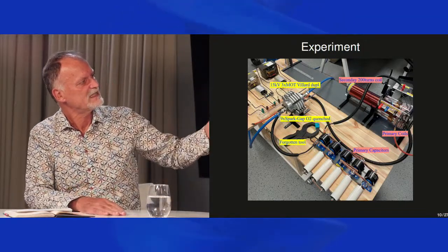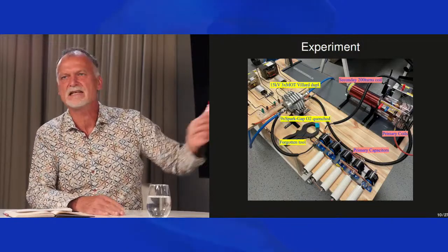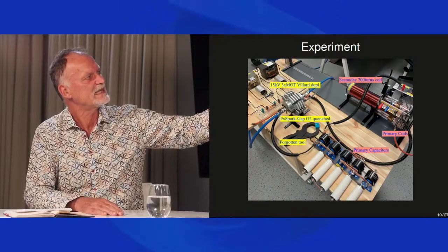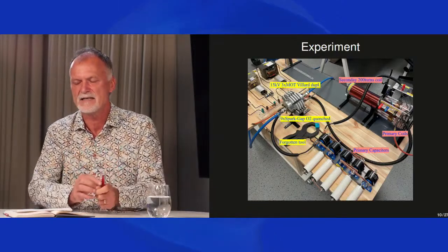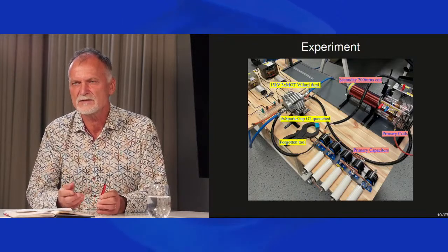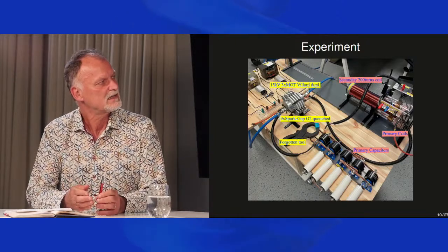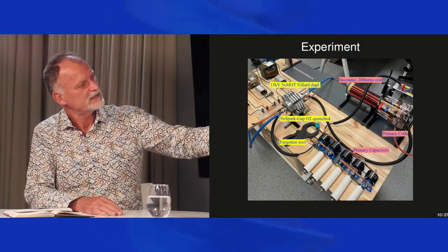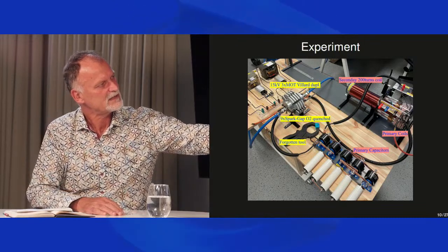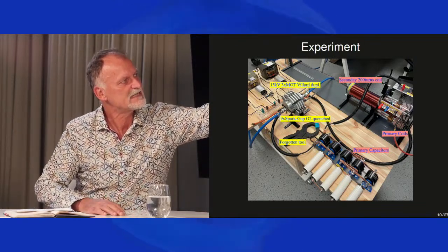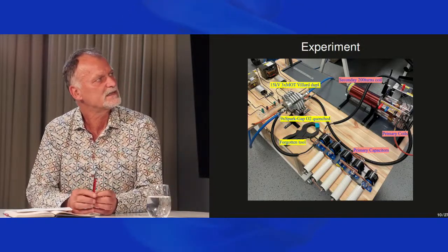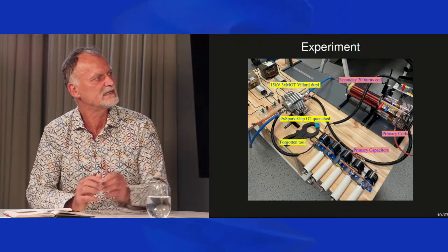Then there is a spark gap here. This is our special design, a 9-stage spark gap, which is very suitable to provide a very sharp, high frequency switch, right? Then we have the primary capacitors here, and this one is the secondary coil. In this case, we have used something with 200 turns, and the primary coils are on that part. It's not so nicely visible, right?